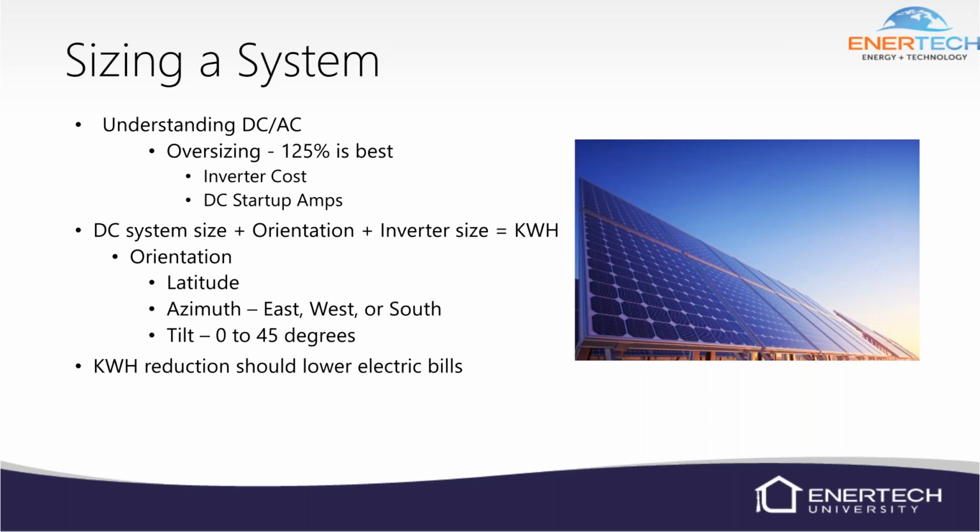All our inverters, depending on the company that makes it, if they're single phase or 3-phase or whatever it may be, they only make them in certain sizes. So, single phase string inverters that we'll talk about later, they're only available in 6 kW, 7.5 kW, or 7.6 kW, 10 kW, and 11.4.